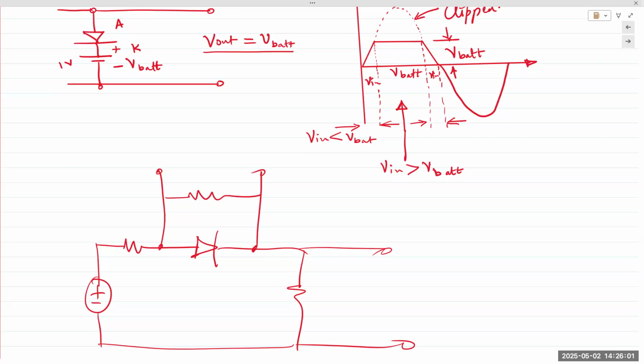One immediate application that comes to mind is using it as a surge protector. If you have a single Zener diode rated at 120 volts, you connect it across the power outlets. If there's voltage fluctuations or a lightning strike, if the Zener diode can handle the lightning strike, of course. But the point is, if there is voltage fluctuation from 120 volts to, like, 130 volts, and you want to protect your devices or appliances, then the Zener diode will conduct, not permitting more than 120 volts to go to the output. So that'd be an example of a clipping circuit. But again, surge protectors have far more complicated circuitry, depending on how well made and expensive they are.